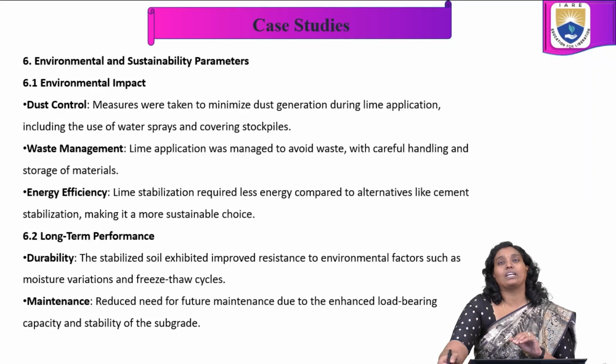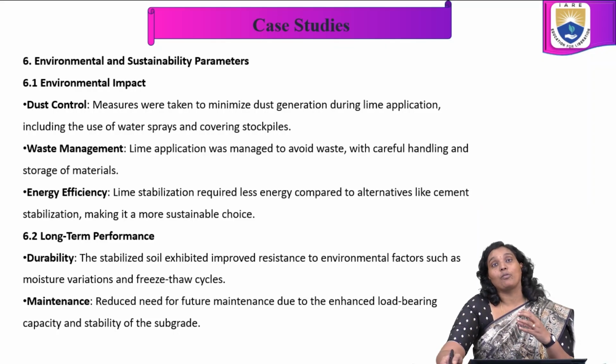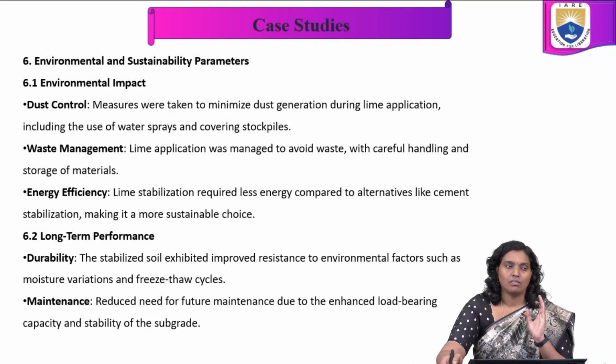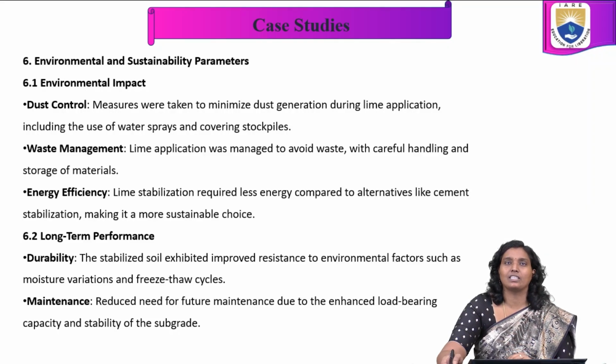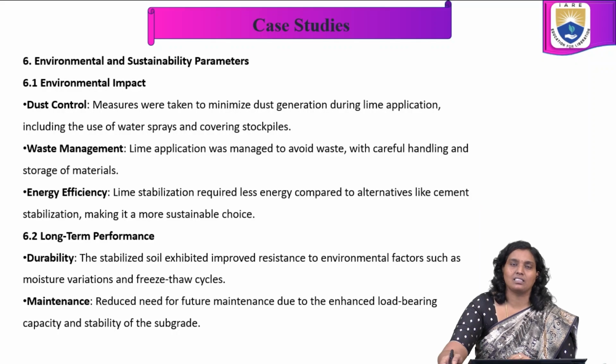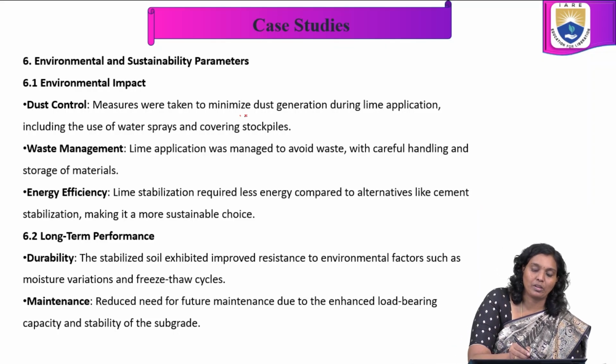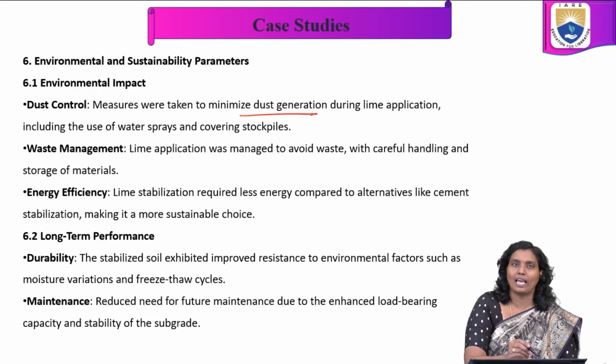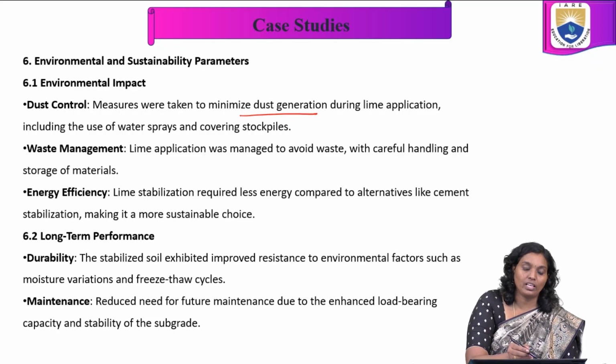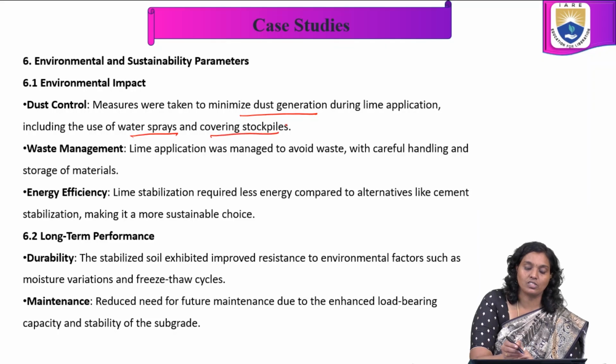And in environmental and sustainable parameters, what kind of environmental impact is caused by this lime stabilization for getting the desired soil properties? In this, dust control, waste management, energy efficiency. In dust control, measures were taken to minimize dust generation during lime application, including the use of water sprays and covering stockpiles.